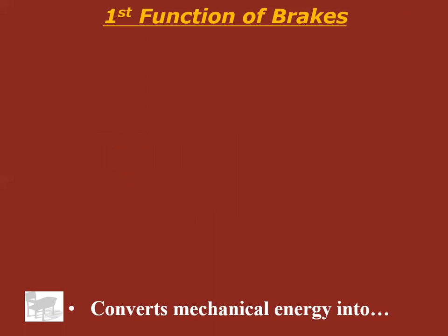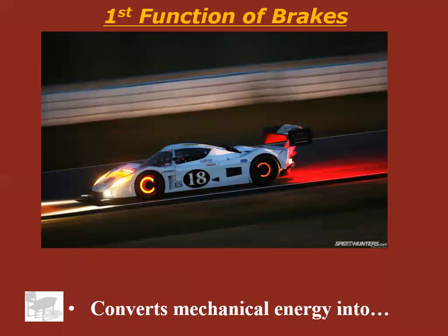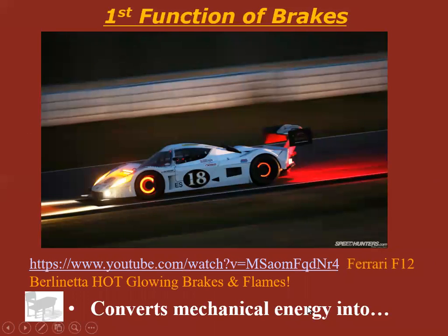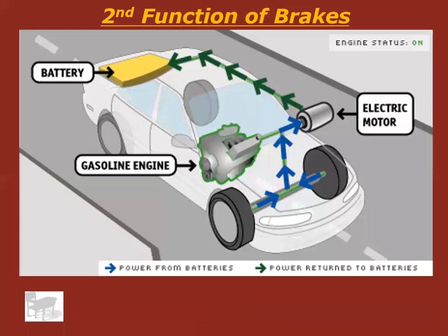First function of brakes is they convert mechanical energy into heat. Okay, mechanical into heat energy. Go ahead and watch this video at this time, and you'll see some heat being generated by brakes. Okay, you should have just watched that video. Kind of neat. You can see the heat coming right off the brakes, and you know that the friction between the pads and the rotors just turns right into heat.